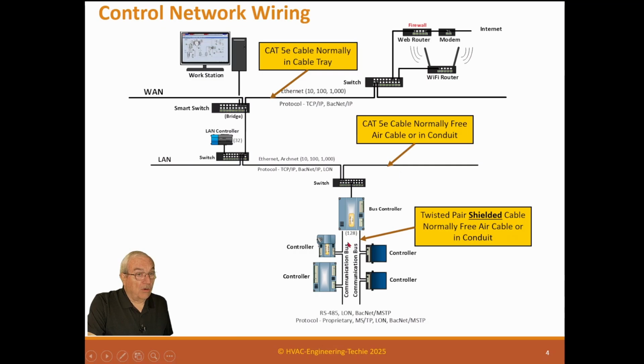Now, these may also be LAN. Traditionally, we use these buses. By buses, I mean it's wire that carries a voltage signal. If it's a LAN, it carries what we call a packet signal. It's a little complicated, but we talk about that in the architecture section. So this may actually be an IP LAN or an Ethernet LAN.